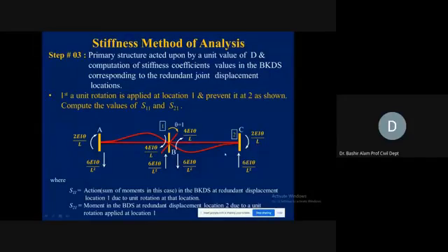The balancing couple for the right span, again, was clockwise, so the balancing couple will be counterclockwise. Its magnitude will be 6EIθ divided by L square. This 6 is coming because of this unbalanced moment addition, 4 plus 2. So 6EIθ divided by L is the unbalanced moment.